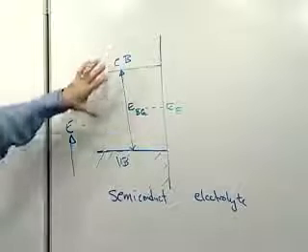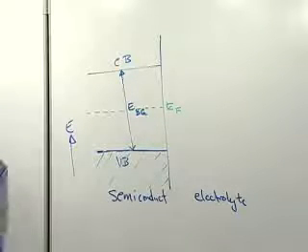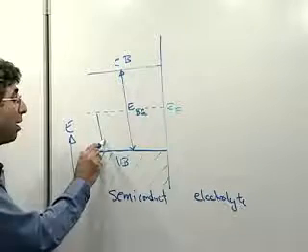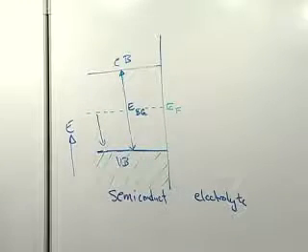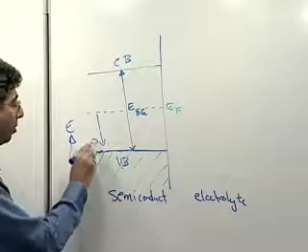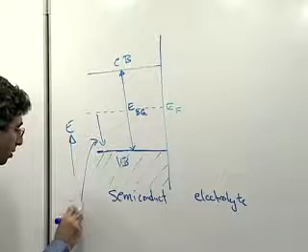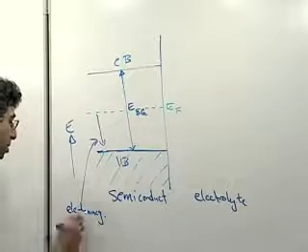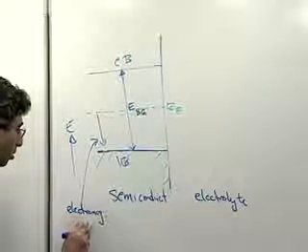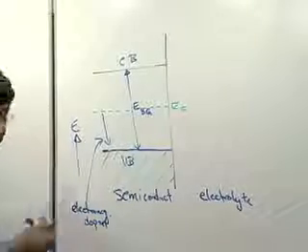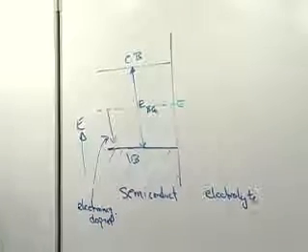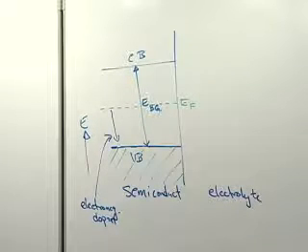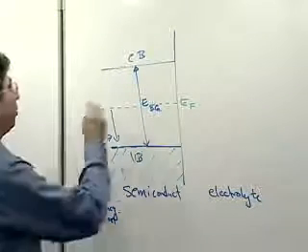If you add a material to this lattice that's going to withdraw some electrons from the lattice, that is more electronegative than the lattice, you move the Fermi level down. Okay? So we're adding something that's electron withdrawing. On the other hand, if we add something that is less electronegative than the lattice, we will donate electrons from that dopant to the lattice, and things move up.